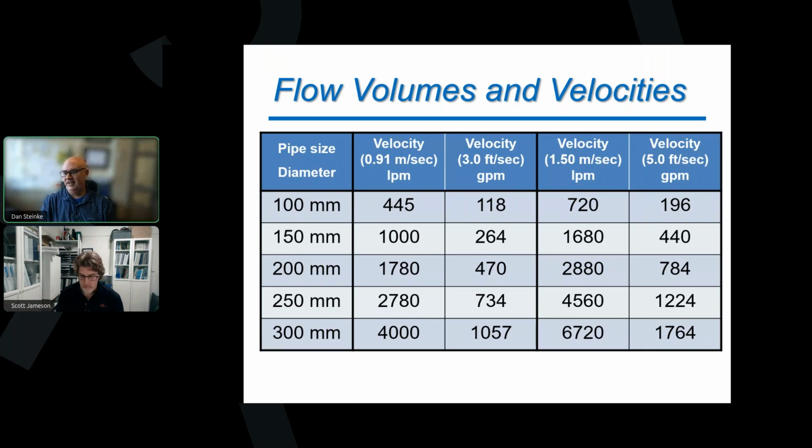All right. Priscilla asks, have you encountered issues with old house lines with lots of sediments, like from manganese and iron? And is there a way to flush the house line? Yes, I have experienced this quite a bit, especially with manganese in systems. For flushing the service lines to the homes, the best thing you can do is just open up every tap that you possibly can on the home and try to flush those out.